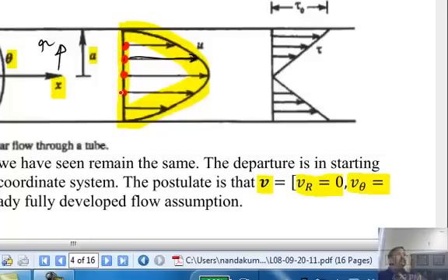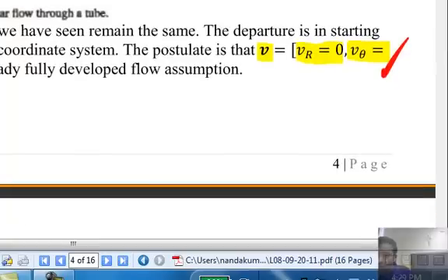It agrees up to a Reynolds number of 2100, no matter what the fluid is, no matter how big the diameter of the pipe is, okay, and no matter what the velocity is. If that combination that gives you the Reynolds number does not exceed 2100, this assumption is perfectly valid. Okay? But if it exceeds that, then that assumption fails. And that's what leads to transitional flows and turbulent flows. Any questions on the problem statement?